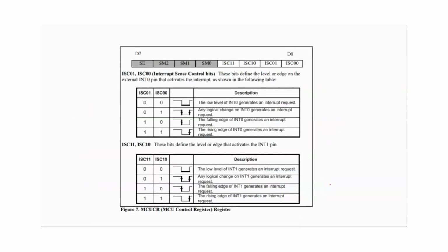So the solution lies here: to consider only one interrupt, we set it as edge triggered. There are two types of interrupts: level triggering, where at this level it will be considered as an interrupt if we set these two bits according to this configuration 00, and if we change these two bits according to these, then it is edge triggered, and now the interrupt occurs according to these edges.